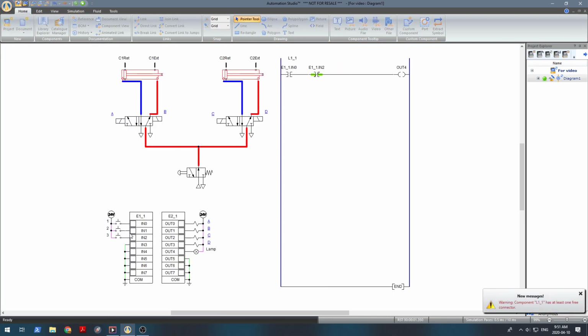And now we can see that normally it's active, and if we press the first button, the lamp lights up. But if we press input 2 and try to do the same thing, the lamp will not light. This has been a brief summary of how to work with inputs with PLC.